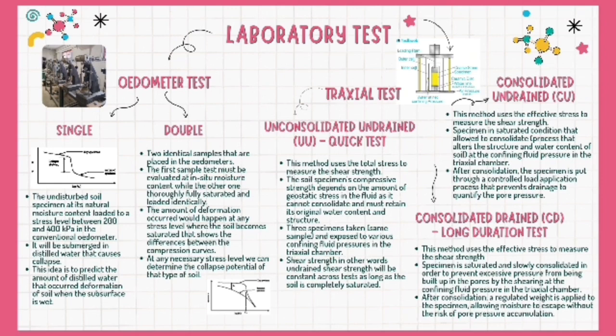The second laboratory test is the triaxial test. This test reproduces the in situ stresses that exist at the sample's original location. The figure shows a cylindrical core specimen, which can be rock, soil, or granular material, that is subjected to a triaxial test in order to assess its mechanical properties and shear strength. The specimen is then sheared to failure to obtain its shear strength characteristics. Usually, the specimen will be saturated first, then consolidated, and ultimately sheared under compressive circumstances.